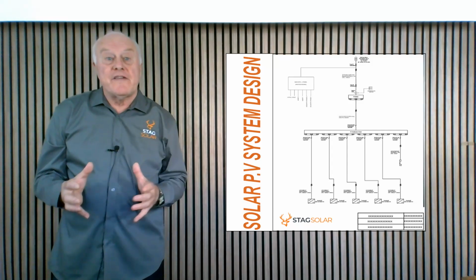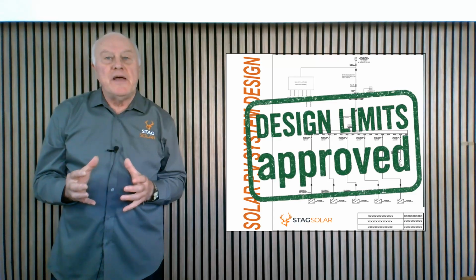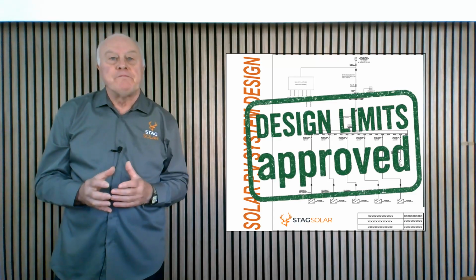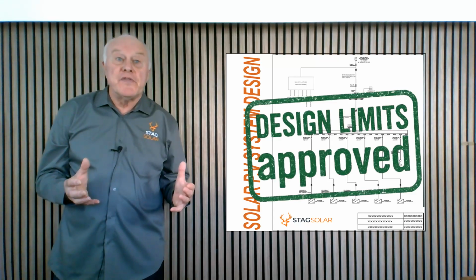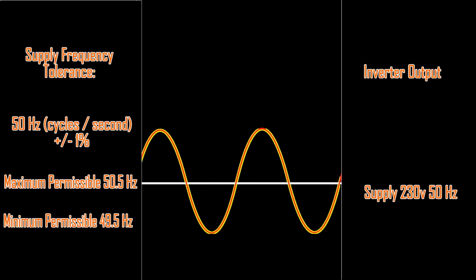So part of our design process ensures that each system we install remains within these limits. And it's a similar story with frequency. Again, there are limits. Only a very tiny error is allowable here. But if the frequency at the inverter terminals either speeds up or slows down too much, the inverter immediately shuts down.